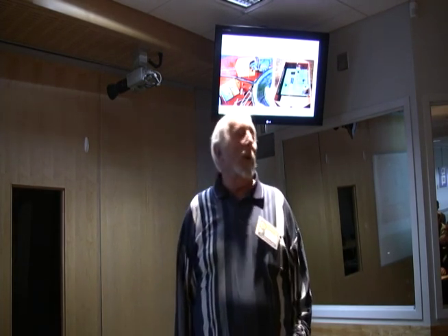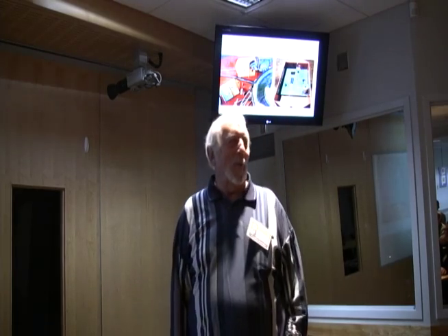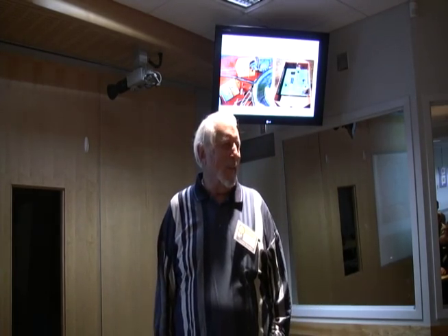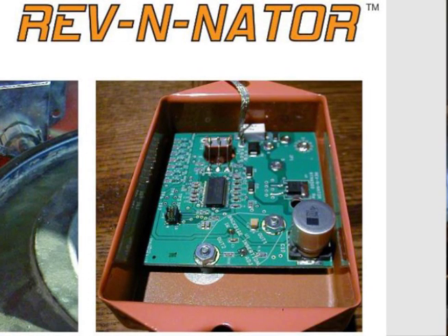Which CAD package did you use for the circuit board layout? OrCAD. Okay. I have OrCAD, I've had it for years. The circuit board layout is simple here, as you can see, but there are some tricks, real important tricks. See this blank space right here that runs around under those parts and down there and around? This foil right here is connected to the coil. When the coil makes a spark, it makes 15,000 volts. And about 800 of those volts make it back down the wire through that pin into our box.